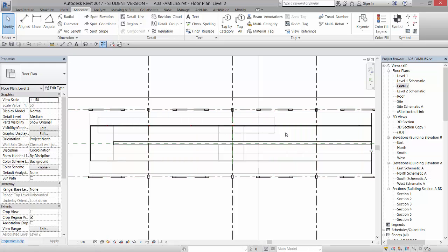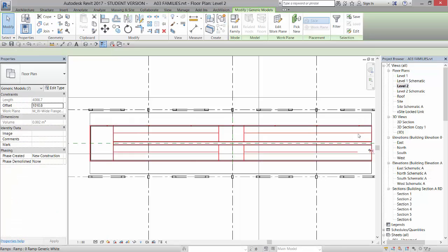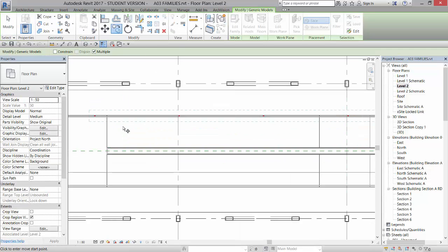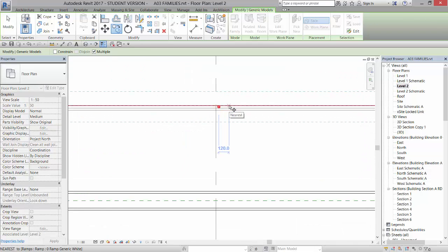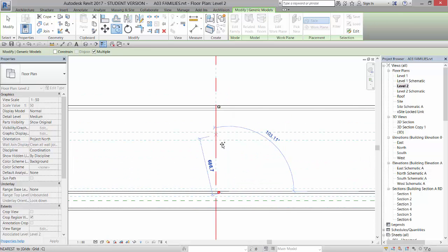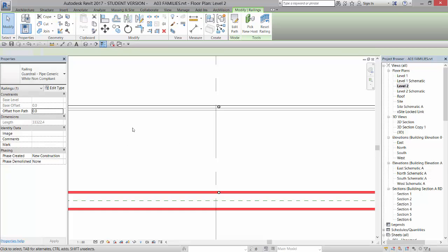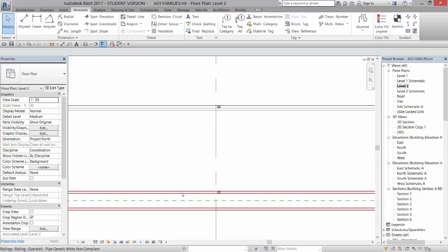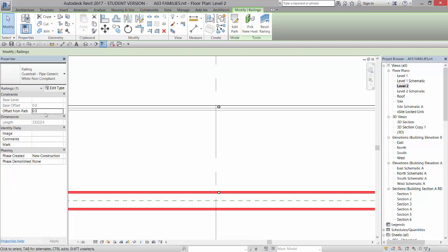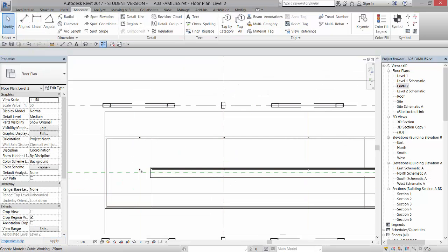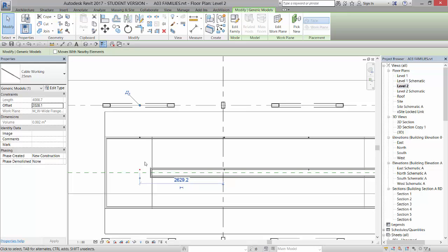So if I select this window around all those cables, I can then copy those from the outside of that to there. And we need to offset this railing the same amount, which this railing is offset by -44. So I'll select this one and offset that by -44 as well. And there we have it. And we can delete this one so we don't need it.